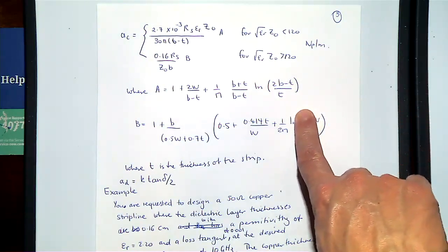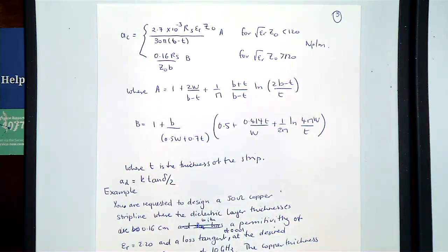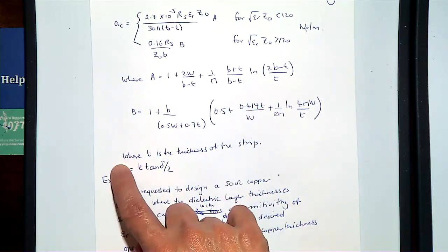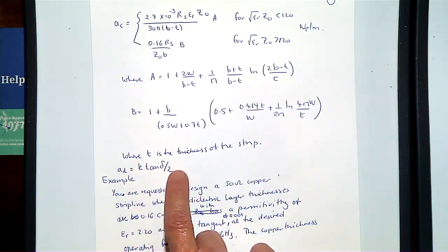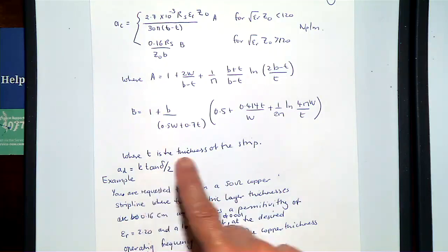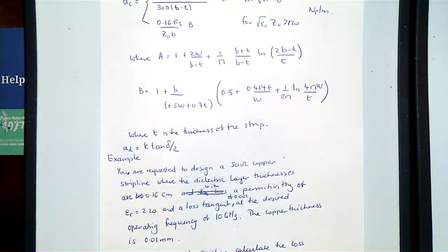And then what we also did was we briefly described what happens when we've got the dielectric constant. Sorry, if we want to work out the loss due to the dielectric, and we rewrote that in terms of the loss tangent of that particular material. And essentially, if you remember, I forgot to bring it today. What we had was I brought up a data sheet and showed to you if you were designing a PCB board, based from a particular manufacturer, what you would look at is, depending on the material that you're using, you would look at the dielectric constant for the frequency or the range of frequencies that you were trying to design your PCB board for, and you would also look at the corresponding loss tangents.